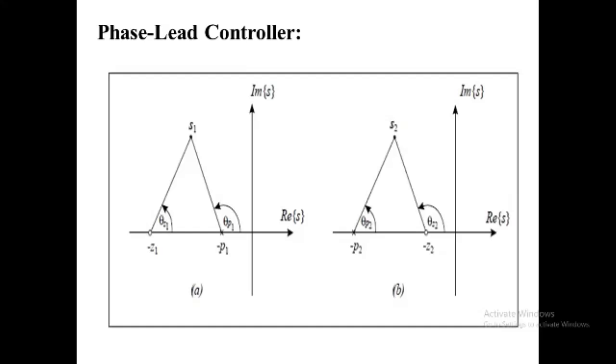Sometimes one is able to improve the control system specification by changing the static gain K only. It can be observed that as K increases, the steady state error decreases, but the maximum percent overshoot increases. However, using a large value for K may damage the system stability. Even more, in most cases the desired operating point for the system dominant poles, which satisfies the transient response requirement, does not lie on the original root locus. Thus, in order to solve the transient response and steady state error improvement problem, one has to design the dynamic controllers considered in this section and put them in series with the plant, or the system to be controlled.